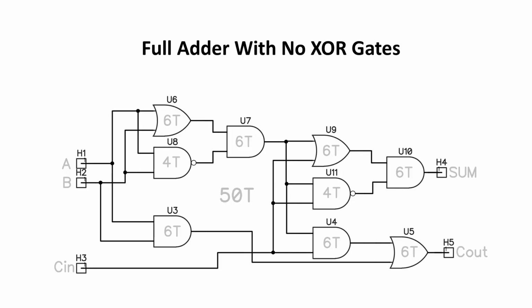Now I've got a limit on how many transistors I can put on each board because my circuit board making program license only lets me put a maximum of 500 points on there. So a transistor would be like 3 points because it's got 3 legs, a resistor would be 2. But they all add up. And it takes space. So I can generally get maybe 130, 140 transistors at the most on one board. So with this, I could only get 2 bits on one board.